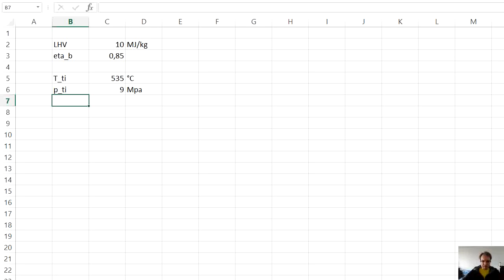And we will have a specified temperature of the cooling water inlet into the condenser, which will be 20 degrees C. Now we will need to specify some temperature differences, which first will be subcooling at the end of the condenser, meaning how many degrees below the saturation temperature the condensate will leave the condenser. Delta T sub will be, in our case, 4 kelvins.